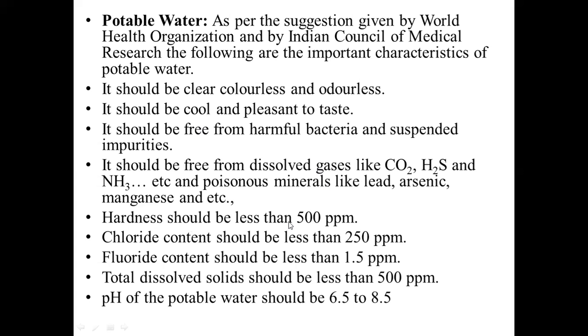should not be there. Hardness should be less than 500 ppm. Fluoride content should be less than 1.5 ppm. Total dissolved solids should be less than 500 ppm. pH of the potable water should be 6.5 to 8.5. That is how it is.